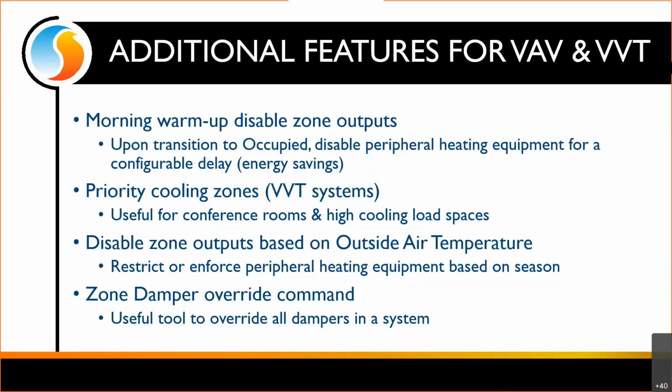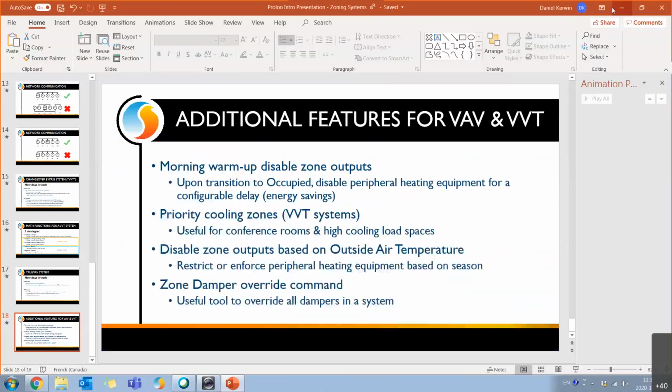And then lastly, we have a tool, which is just a zone damper override command. If ever we want to force all zone dampers open or closed, we are able to do it from the software without going up to each wall sensor or up to the VAV controller and playing with set points. We have a central command. So that's about it on the PowerPoint side.